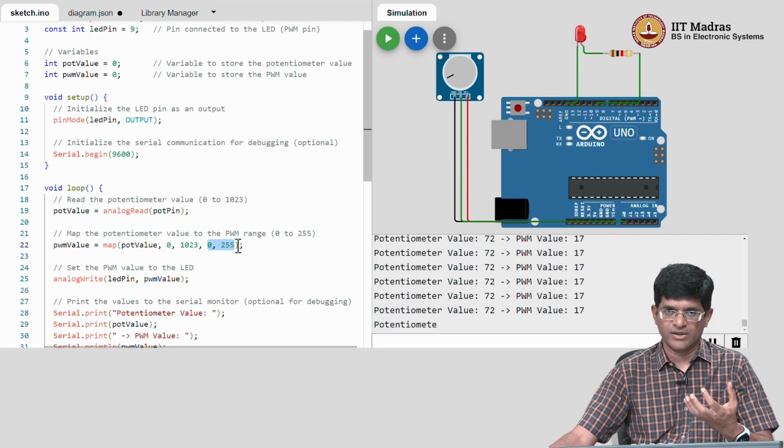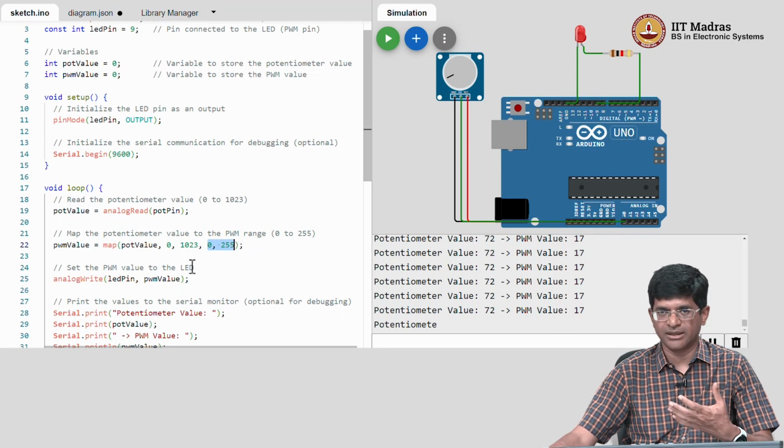So these are trade-offs. What the Arduino ecosystem has done is say that for most practical purposes, at least for a lot of useful applications, having this simplicity allows you to get started much more easily than worrying about every single setting inside the HAL of the system. Not only that, this code could pretty much be migrated into the STM32 series with very minimal changes. All that somebody needs to do is figure out how to write an analogWrite function over there, which will automatically set up the timers for doing pulse width modulation, assuming that they take a value in the range 0 to 255.